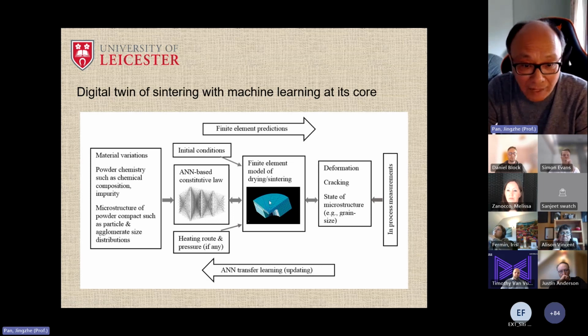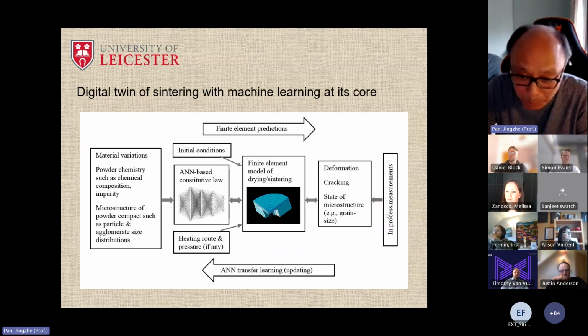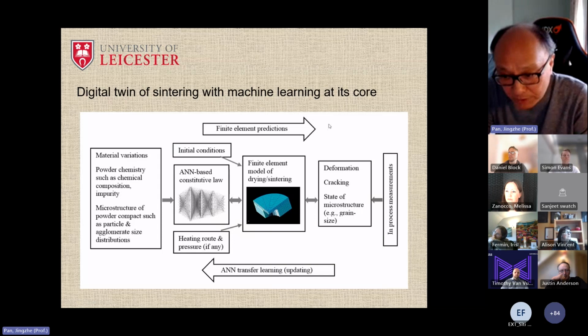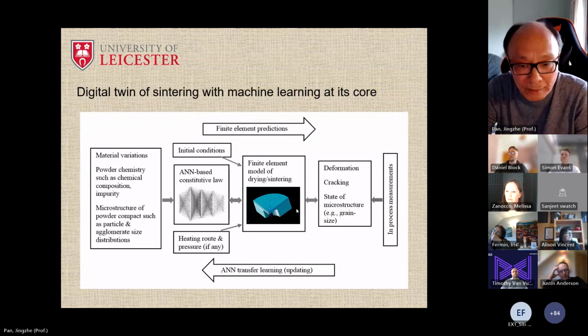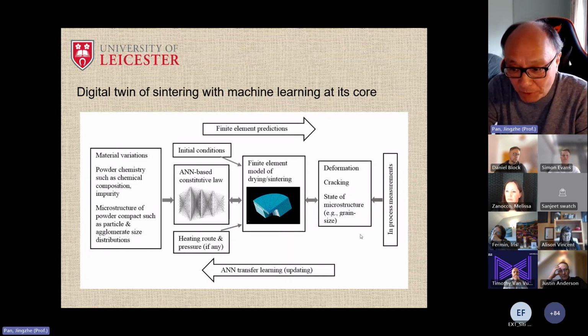And the problem I have is that the parameters we plug into this model are uncertain. So in the digital twin strategy, we want to collect data in the manufacturing process. We call it in-process measurement. If we can collect data from the manufacturing process and do back propagation, we can work backward rather than forward prediction. We do backward updating, and if we can modify and refine the model, that makes this mathematical model a digital twin.